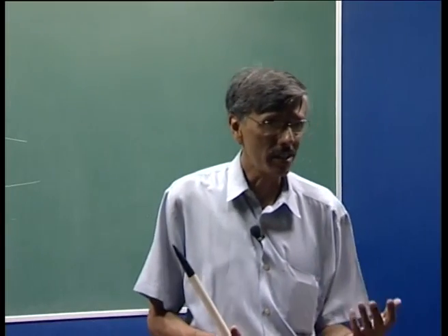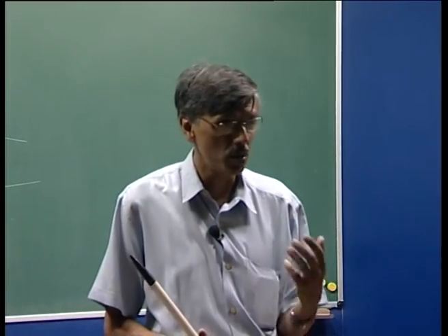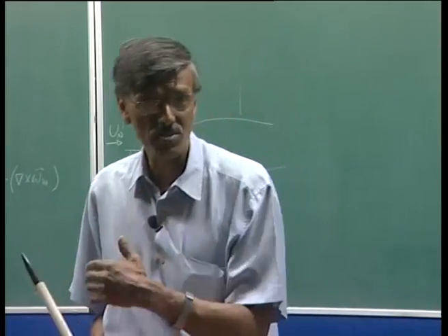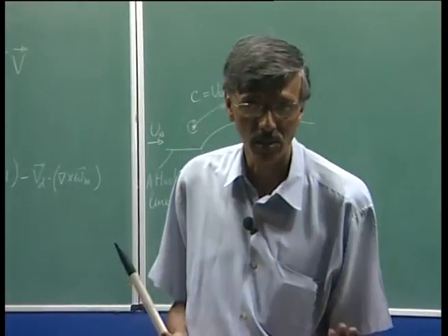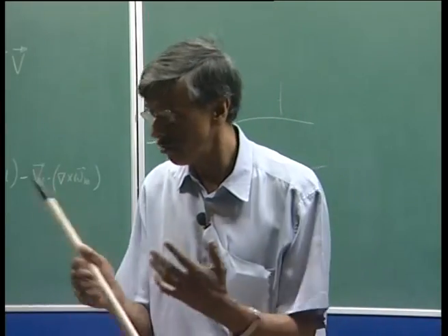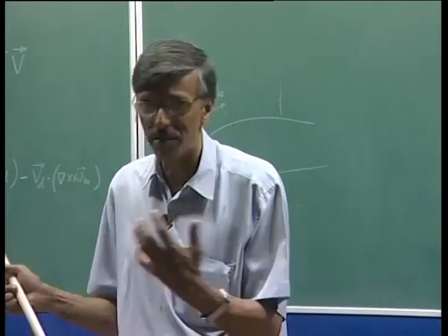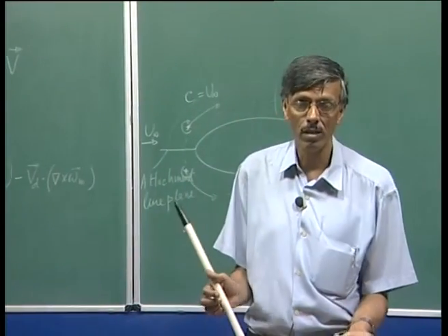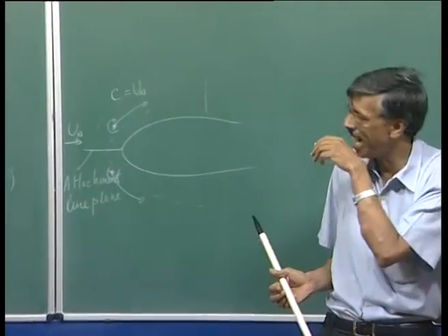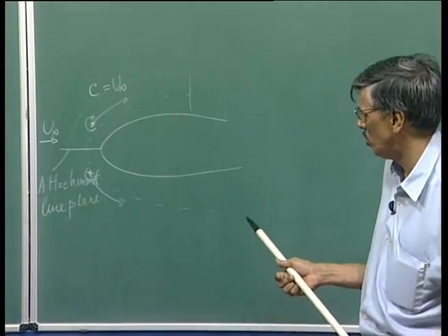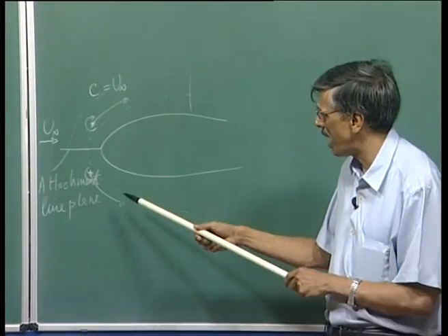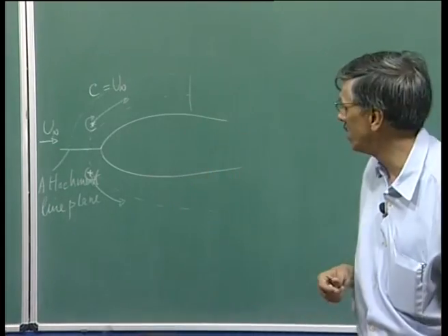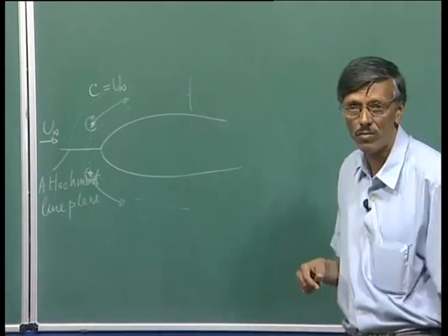And over the wing, you are basically talking about both mechanisms being present. So, we are talking about if there is a streamwise instability, if there is a cross flow instability, or a combination of the two. Everything should be picked up by a 3-dimensional direct simulation of such a flow. So, that was perhaps attempted in Obrist and Schmidt, but they did not see any effect of it.